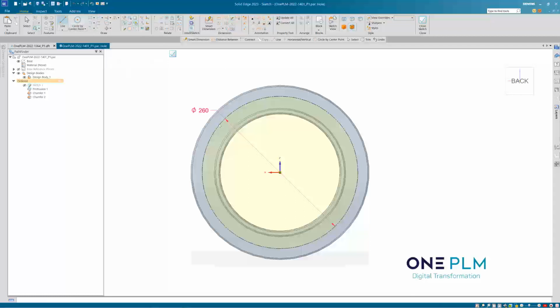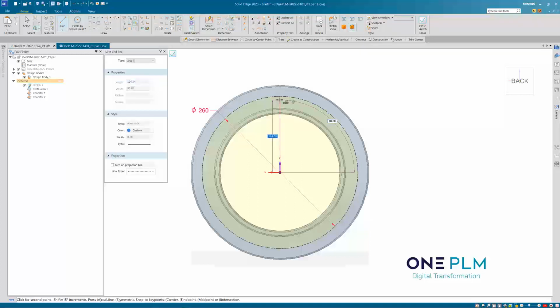And then for this one, we need to position the holes in certain locations. So this first one needs to be at 10 degrees. If I press the tab key and go to 80, that's going to allow me to create a line that goes to there at that value. Then right click, start another line, and there. And I want to create 4 lines going across here like this.